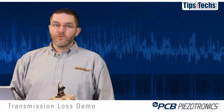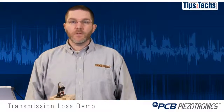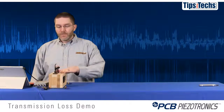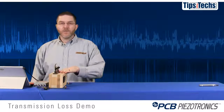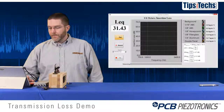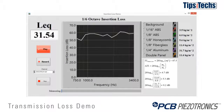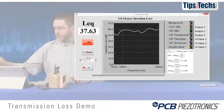The first thing we're going to do for this demo is determine the maximum insertion loss that we can measure in this room. We'll do that by playing a sound through the speaker and then measuring the background noise in the room and subtracting the 2 levels. So first we'll play a sound. Now we're just going to record the background noise, and the program has automatically subtracted those and plotted them on the screen for you. So you can see the maximum insertion loss that we can measure in this room is about 60 decibels across the frequency range shown in the demo.